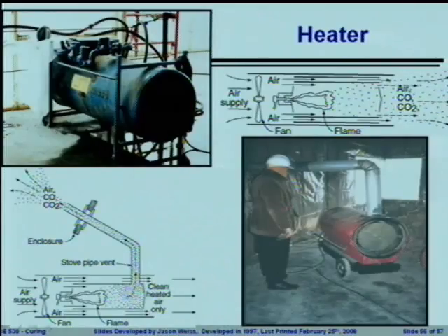One last thing that I will mention, if you have to heat an enclosure, is that a lot of these internal heaters tell you to vent them properly. Venting them properly means venting them to the outside, and it is very common, especially on smaller construction jobs, for these not to be ventilated properly. If they're not, you are robbing the inside of oxygen, and people who may be inside like oxygen. You like oxygen. I like oxygen.